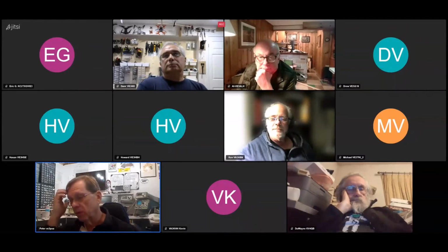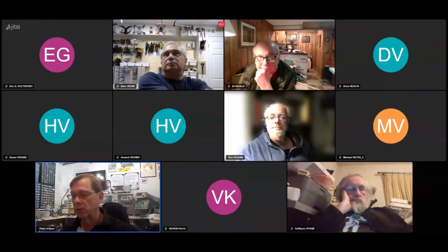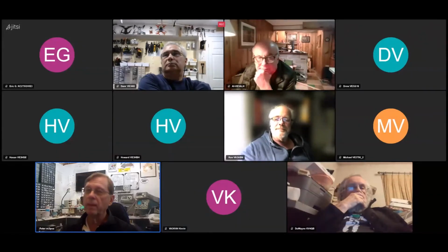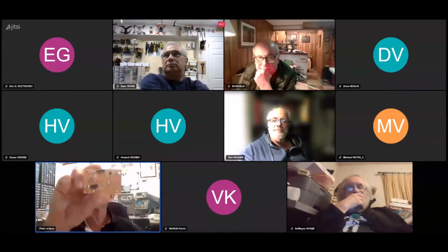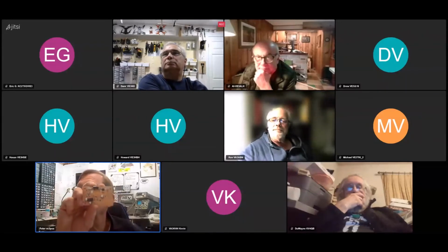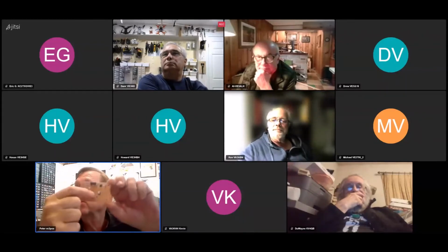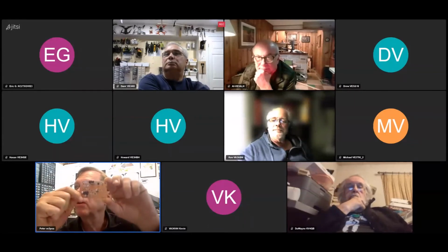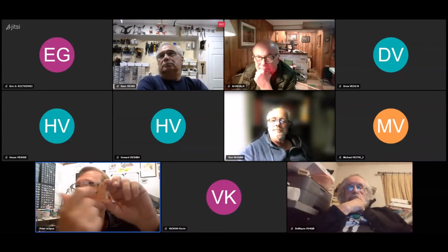So I looked into it a little bit further, and this is where I'm blaming Dave, because Dave asked me to proofread a circuit of his, and he forgot one trace. And all of a sudden now I forgot a second trace. So what I thought was going to be a nice looking little board turned into a little bit of an ugly board. But anyway, there it is. It's pretty hard to see the repairs. There's a repair up there, one trace. And underneath that cap is where there was the missing trace. Down there is the transistor, the 3904, and of course the LM386.